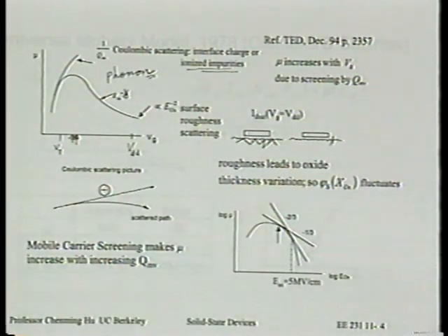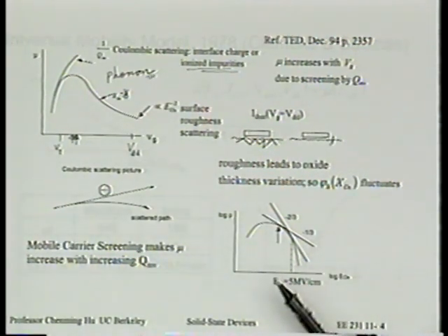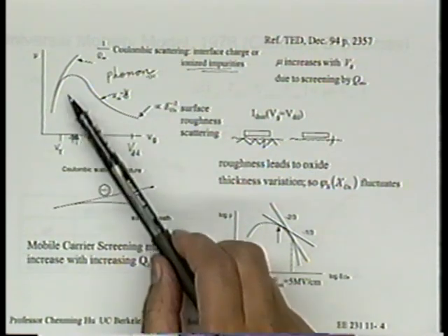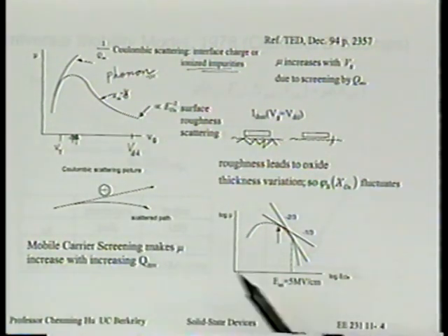Well, it turns out part of the reason is the topic of the next section, which saves the day. That is, because of velocity saturation, current is not truly proportional to mobility, fortunately. If it was, we would have bigger problems than we are in, all right? But fortunately, the current is not proportional to mobility. Of course, current is affected by mobility quite significantly, but it's not strictly proportional, all right? So I'm just emphasizing how important this dependence is between VG and vertical field.